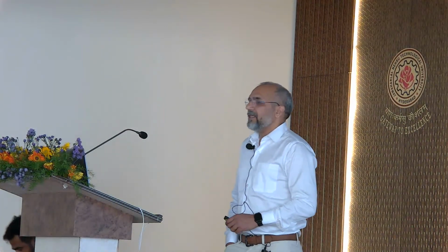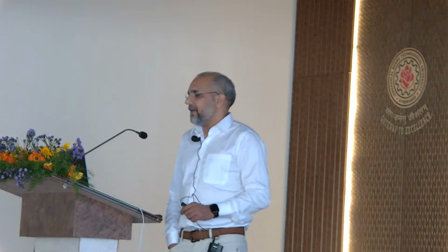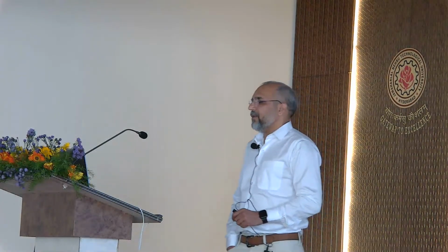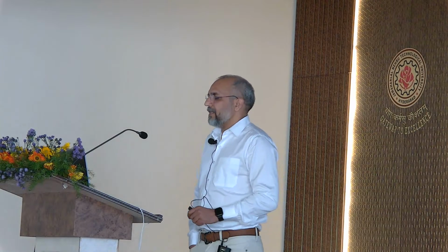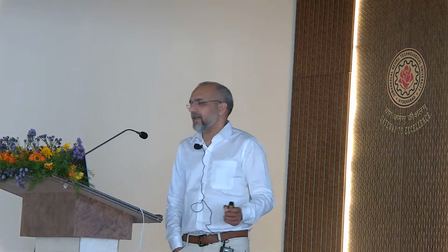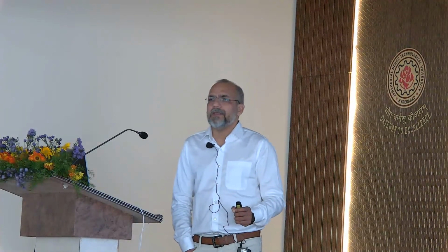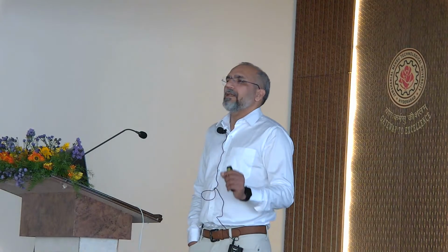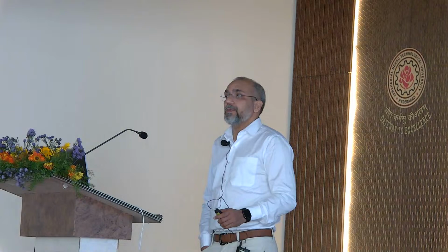When we talk about physical vapor deposition, there are different subcategories like sputter deposition, electron beam deposition, thermal evaporation deposition, arc evaporation method, or pulsed laser deposition method. Each type of these PVD methods is similar in terms of working mechanism, but they have a different procedure. When I say different procedure, I mean the way they evaporate these molecules, that technique is different. Otherwise, the mechanism is the same.